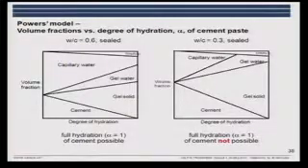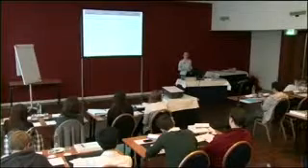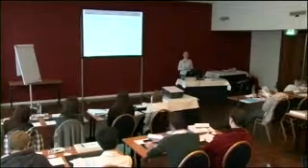And what we see is that, assuming that we cannot use the gel water, we cannot have full hydration of the cement. So when you're preparing your samples for experimental investigations, you should consider this: both whether or not you keep them saturated or sealed, and which water-cement ratios you're using.